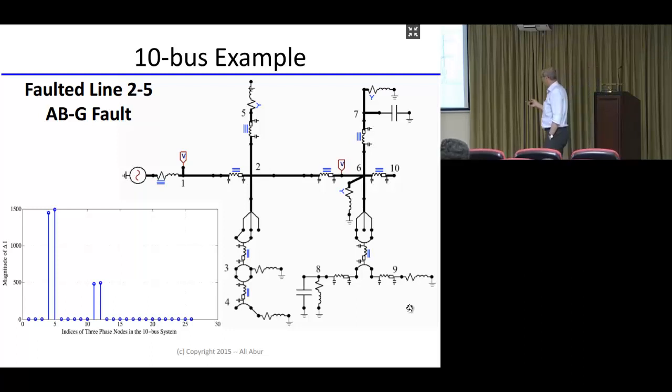As you know, in the US, unlike here, the distribution systems most of the time contain a mixed number of phases. The distribution system may start as a three-phase system, and then eventually it may become a two-phase feeder, and then finally a single-phase feeder. So you may see along the same feeder three-phase, two-phase, and single-phase sections. This is an example where this is the case.